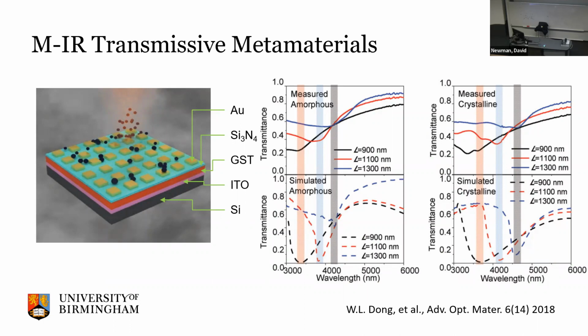As you can see here, these are the simulations of where the resonances should be, depending on the size of these plasmonic resonators. Intrinsic silicon is transparent in the infrared, so this should be quite a transparent material with nice sharp resonances. But when we did the experiment, although we did see some dips, the resonances have a very low Q factor.